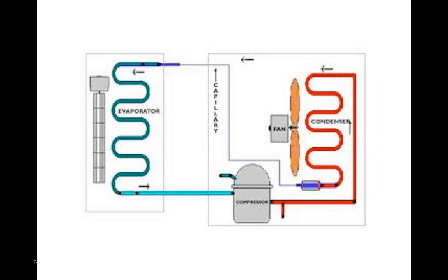The compressor is a device that takes the gas and, as the name implies, compresses it. It either uses a piston or a centrifugal device to compress the gas, so it's very hot. You know, when you compress gases, they get hot. So it's very hot. It's still a gas, but it's very hot. So now you have to change that back into a liquid so you can reuse it.